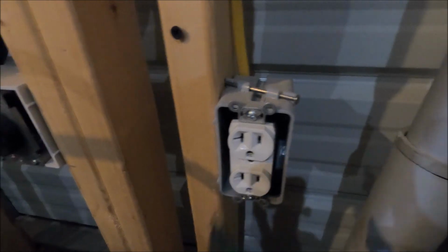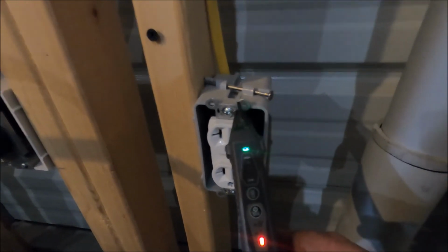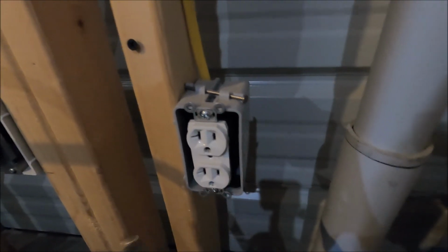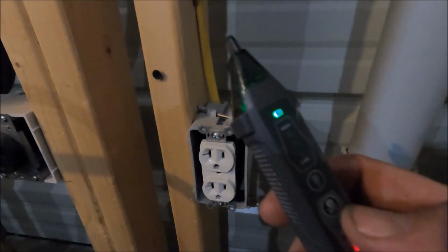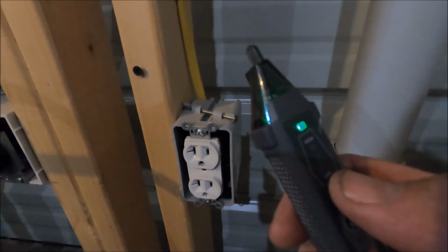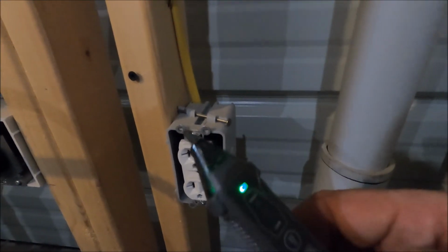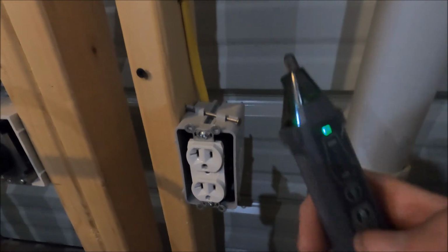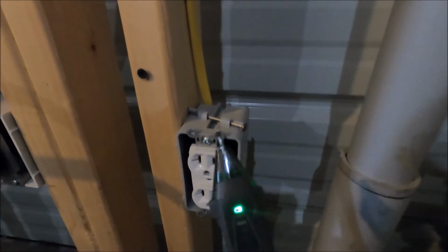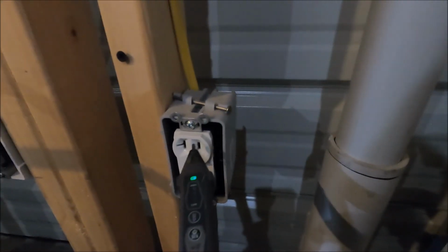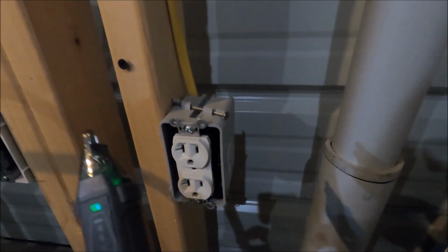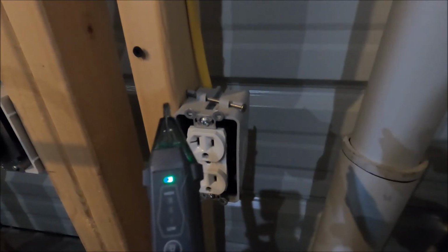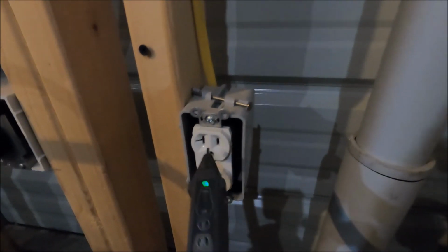How I usually use these is I go find something that is on, so I know that this outlet is live. To test it, I won't just turn it on, because maybe it's not working properly, or some of them don't actually have a light that turns on. You'll just turn it on and you don't know if it's actually working or not. If you're ever going to use one of these to see if there's a live circuit or any power in a box you're working in, take it and test it against something that you know is live.